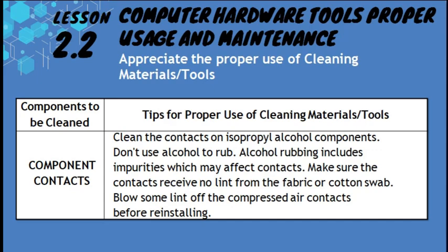Component contacts. Clean the contacts on components with isopropyl alcohol. Don't use rubbing alcohol, as it includes impurities which may affect contacts. Make sure that contacts receive no lint from the fabric or cotton swab. Blow any lint off the contacts with compressed air before reinstalling.